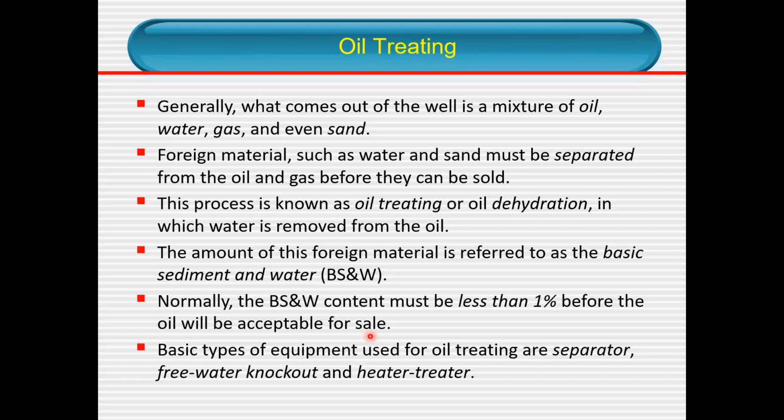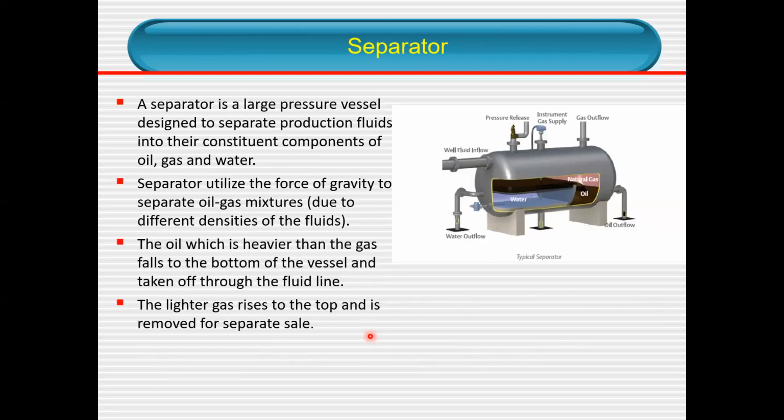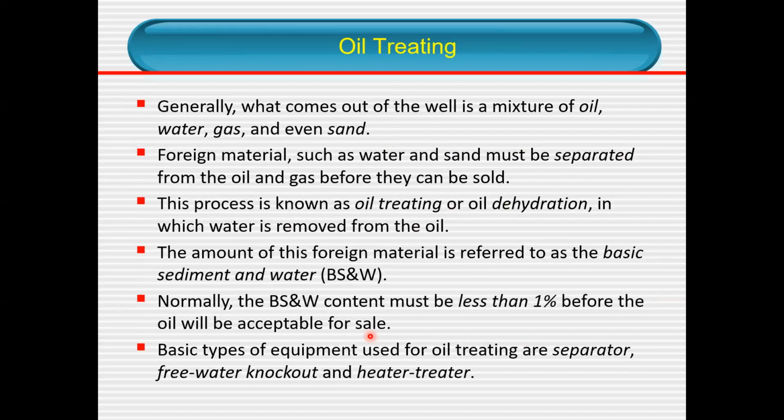Definite no, because of the footprint. And others like ESP, as I explained earlier, only two of them are being tested currently. As you know, many of our old wells have unconsolidated sand, and sand is not good for ESP. Hydraulic pumping is quite expensive. It can be used, but it is quite expensive. So these are the reasons why gas lift is the main one being used in Malaysia.